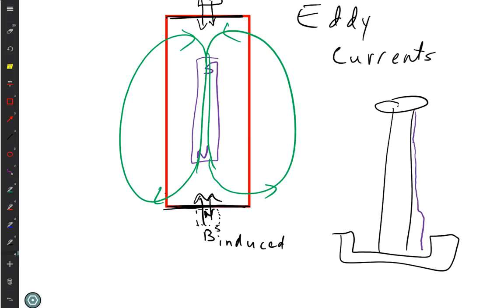If you look at it analytically, it's going into air resistance. You have to put in energy at the same rate, so your power has to equal the power being lost to air resistance if you're on a level surface. And so you're not recovering any of that in an electric car on the freeway. So they get worse performance on the freeway as compared to city driving, whereas a normal car actually gets better, because you're constantly throwing away energy in city driving, whereas you're not constantly throwing it away driving down the freeway.